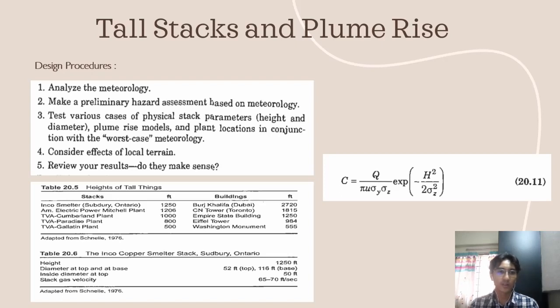Third is to test various cases of physical stack parameters, height and diameter, plume rise models, and plant locations in conjunction with the worst-case meteorology. Fourth is to consider effects of local terrain. And lastly is to review your results, whether they make sense or not.